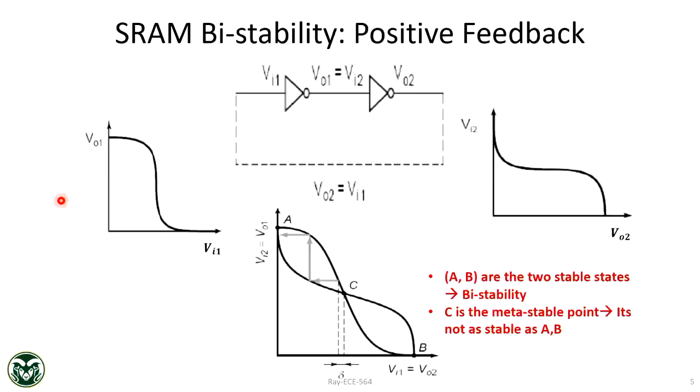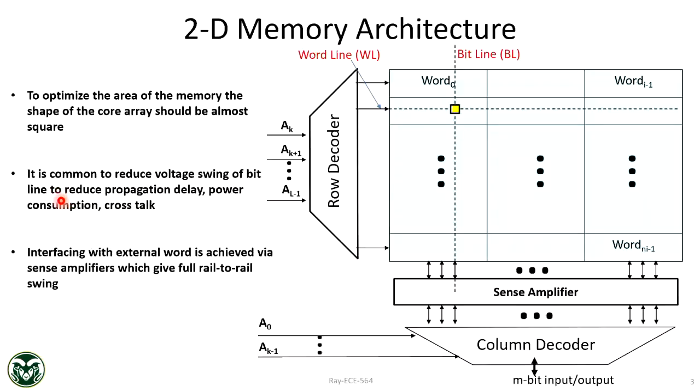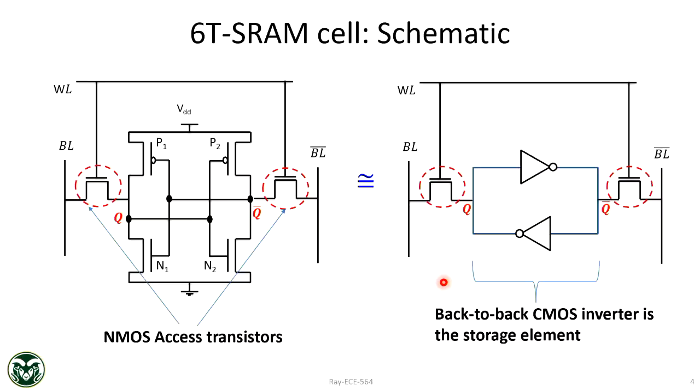So that's why understanding this structure is important. This is 1 bit line, and 1 bit line is a long line shared by many word lines. But you are looking at a particular cell now, right? The capacitance of this bit line will be significantly higher. That's why charging the bit line will take a lot of time and a lot of energy, because it's a high capacitance, right?